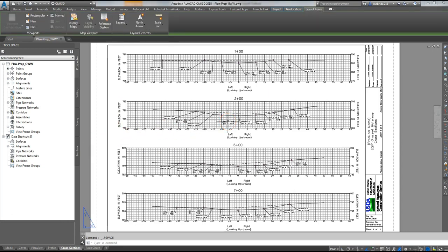The cross-sections are sort of a debatable area on whether or not to put them on plans. Technically, according to specifications, we are not required to put the actual cross-sections on the plans. We are required to put a typical cross-section shape, which you saw on the profile sheet, but we're not necessarily required to put on a cross-section sheet of what's existing and what's designed. So that's really your choice. I will tell you this, after working with some experienced technicians, that this makes your life much easier and much more simple when you're out there construction checking a grass waterway as it's being built.